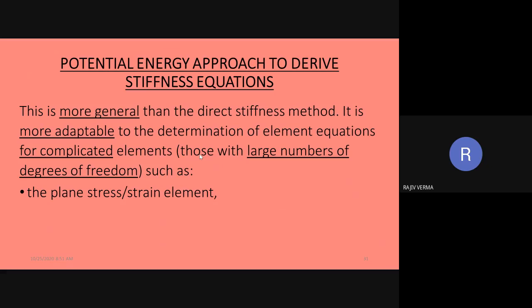Of course, there are higher variants of triangular elements also, but this has just been quoted at the present point from the discussion point of view. So for the case when we are dealing with plane strain or plane stress problems and we are taking a triangular element, we are not going to use the direct approach, but we are going to apply the potential energy approach for the formulation.